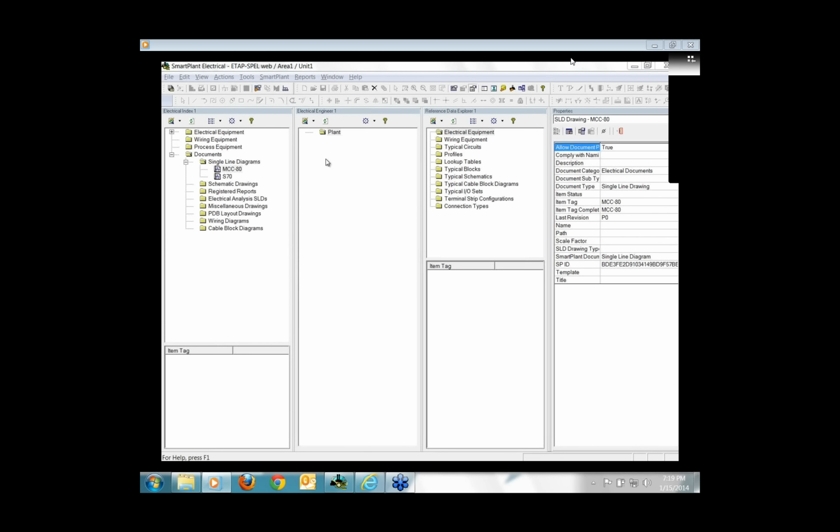After adding the new feeder branch to MCC80, we can reopen the SLD for MCC80 and review the change, including using the compare feature that can compare the current drawing data with last archive revision data, presented to the user in a comparison report spreadsheet and a cloud symbol in the SLD drawing for each changed property. To open the SLD and see the new feeder branch, right-click on the SLD document MCC80, and from the shortcut menu, select Open.